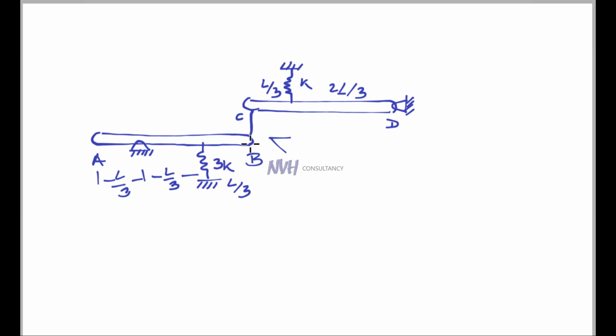Suppose a clockwise angular displacement is given on AB, let's call this angle theta. Once you give a clockwise displacement to AB, that will produce anti-clockwise displacement to CD, and so it will also make an angle. Let's call this angle phi. So this is the configuration.